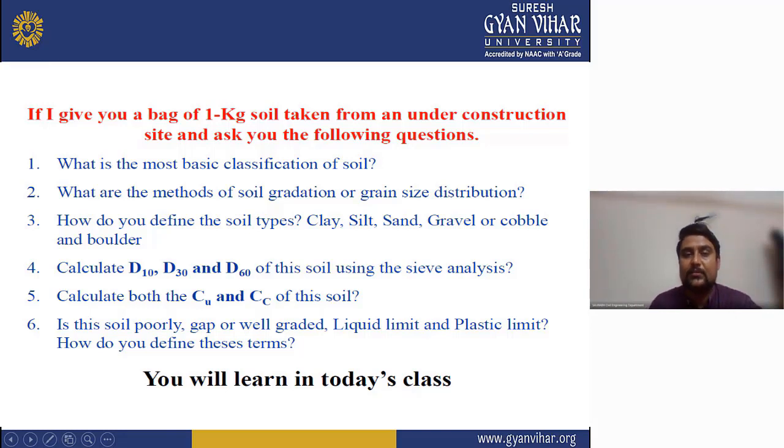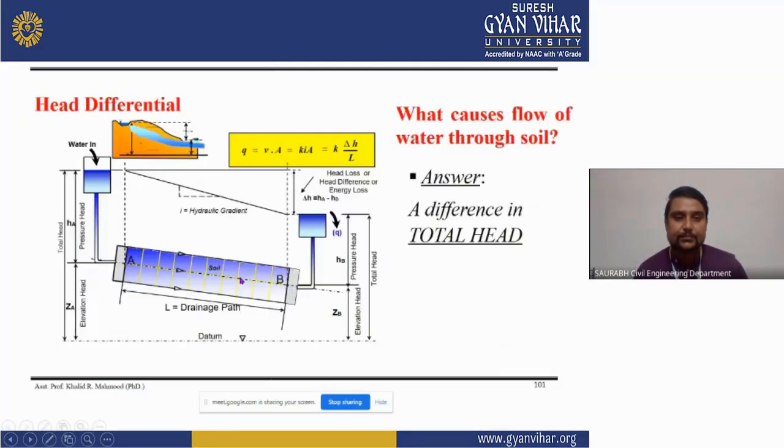Now we will see the sieve designation. What is the meaning of large sieve designation? This sieve is 3 inch, and it is larger. It is used for larger size boulders, and it can also be used in the sieve analysis. Smaller sieves are numbered according to the number of openings per inch.